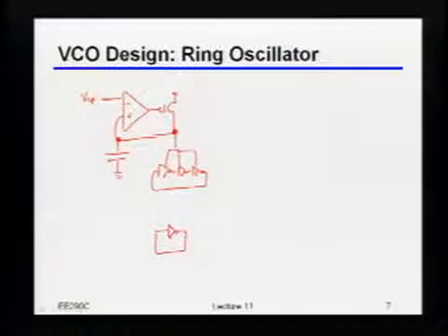Is it because the metastable points of the 3 inverters are not the same? No, not exactly. Let me give you a hint. Let's say that somehow I get an edge into there. What do I want to make sure happens if I want this loop to actually work? With the single inverter, the gain of the loop is less than 1 because you won't fully charge back. You kind of went in the direction I'm getting at, but I want just the digital explanation. So you want that edge to go sufficiently high up before it feeds back.